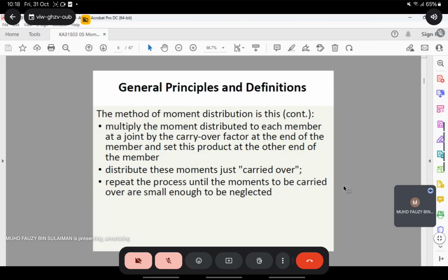I think Dr. Andrew already explained to you what is the function of Eurocode 1, what is the function of Eurocode 2. Eurocode 2 is the one that we design the beam. You find the K balance, you find K less than K bar or K more than K bar. If K is less than K bar, compression reinforcement is not required. If K is bigger than K bar, compression reinforcement is required. I think you already studied this, explained by Dr. Andrew, right? Apa itu Azrin? Eurocode 0, Eurocode 1.